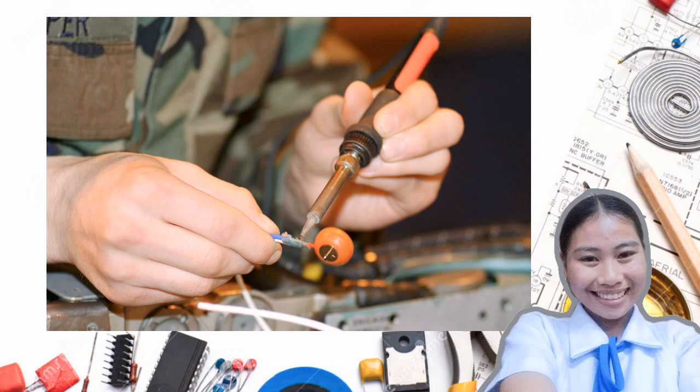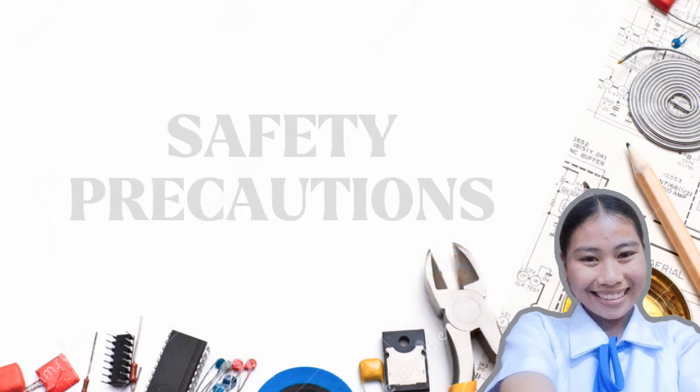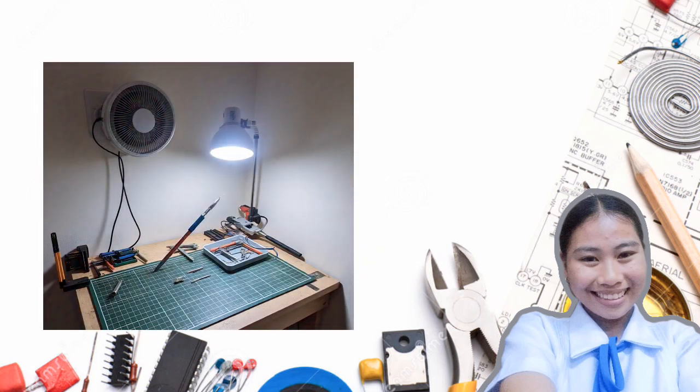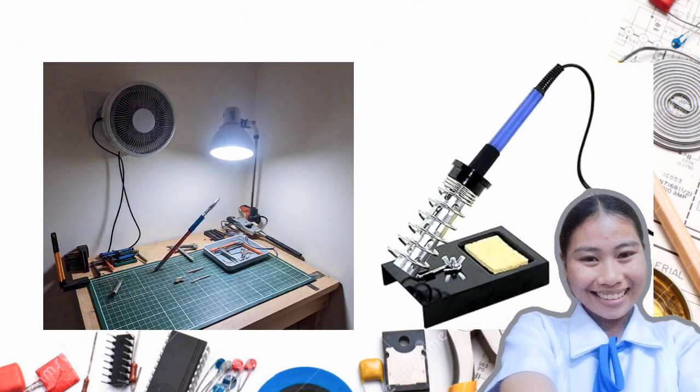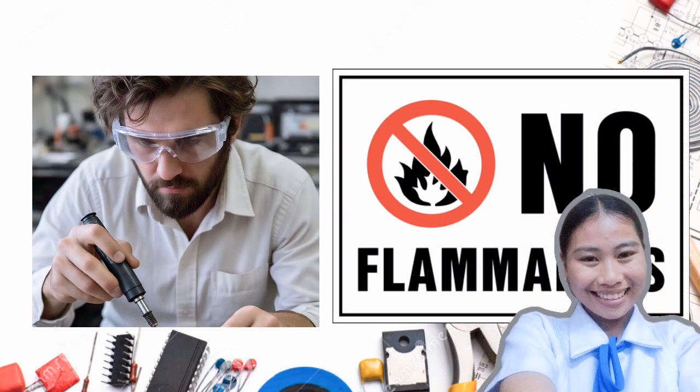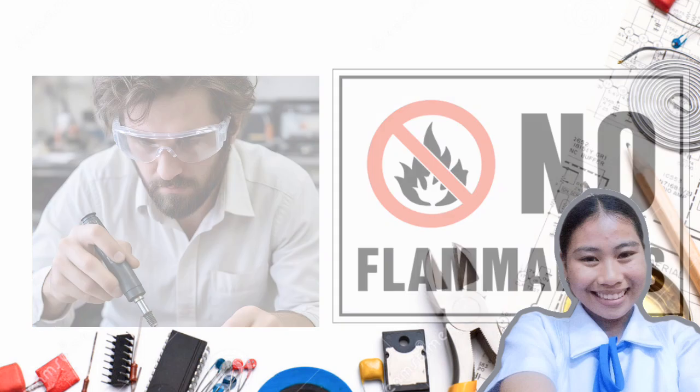Soldering is an important skill in electronics. Before we start, here are some safety precautions. Ensure proper ventilation in the workspace. Always use a soldering iron stand when the tool is not in use. Wear safety goggles to protect your eyes. Keep flammable materials away from the soldering station.